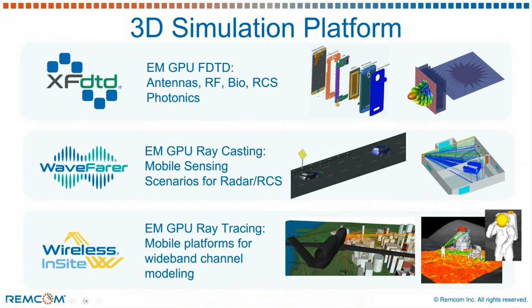Furthermore, we're looking at communications between astronauts with the utilization of placement of antennas on the suit, and looking at side link of communications between astronauts, which utilizes fields that are simulated using XFdtd or measured in a chamber, namely from MVG, and we bring those over into the simulation space with the material, with the de-embedding, and place that near field source, including the antenna and the tangential E and H fields of the antenna on the body, and place it in the environment that could be on the surface of the moon.